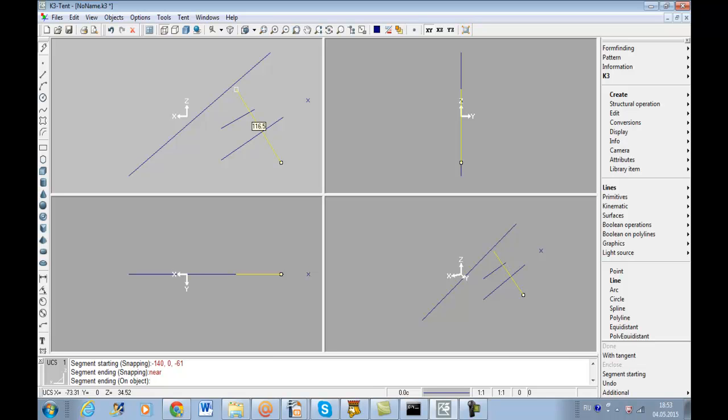In most cases, we do not want to turn on all the object snaps while modeling, as we could accidentally snap to a point we don't want. For example, the ending point and perpendicular point could be very close, so we need to be careful when using perpendicular. And now, let's do a bit of training.